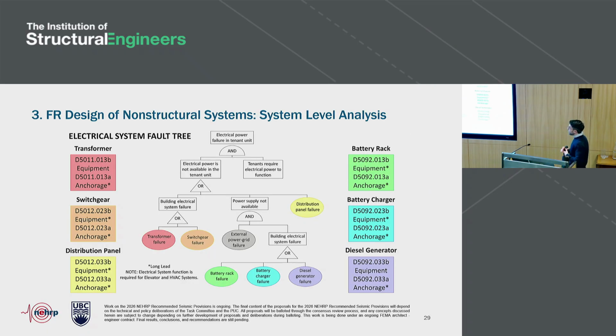You might be wondering how we determine whether non-structural systems are functional or not. So I just wanted to quickly showcase another fault tree, similar to the one that I showed earlier for the structural system, to give you a sense of how this works. For different structural and non-structural systems, we're going to have diagrams like this one that relate component level damage to system level functionality at the top.